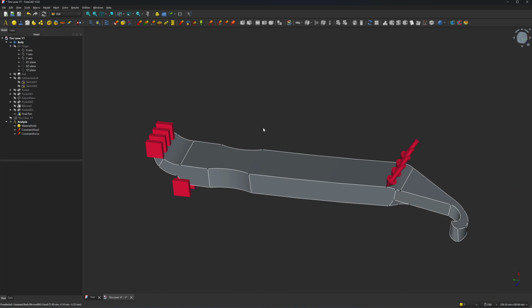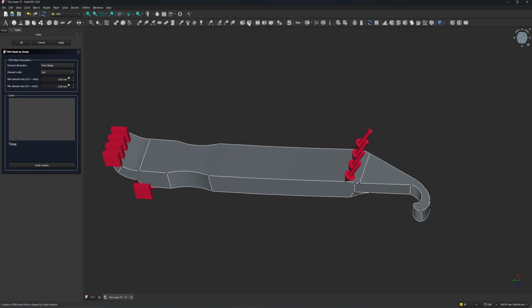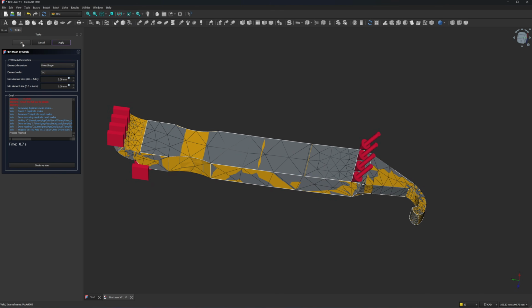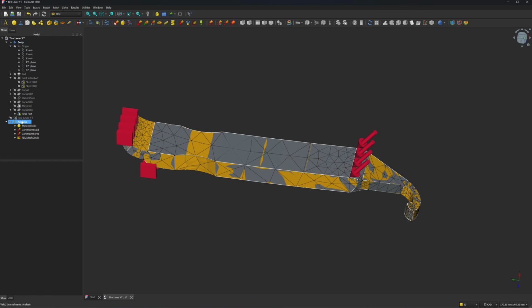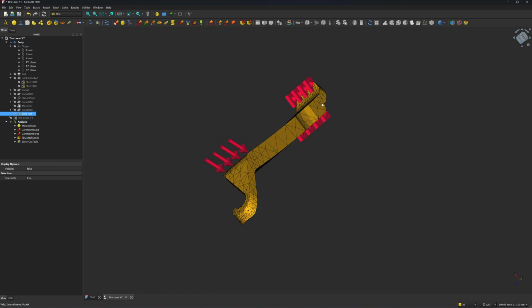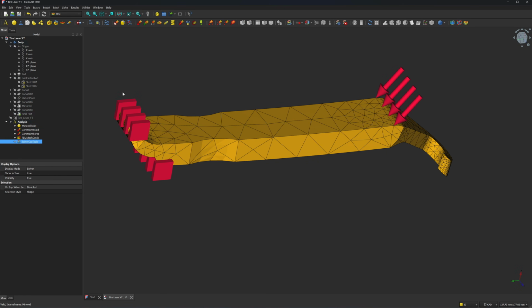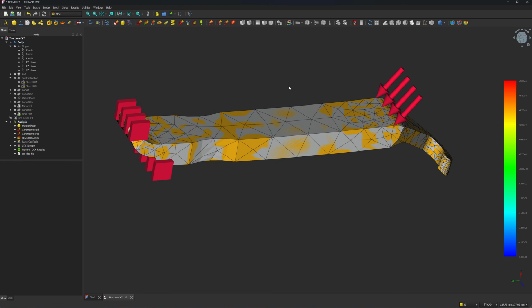Now we have a constraint, we have force, we have materials, almost everything that you are going to need to mesh this model. Click on the final part, the part that you just made. They have two modes, N and G. Let's do the G because the N doesn't work. Let's click on apply. Okay, so I'm going to click on OK, and then I'm going to click on the solver. Let's turn on the final part. The G mesh looks better than the N mesh. Let's try if it works. Click on solver. Click on here. Okay, it works. So if the N doesn't work, try the G.